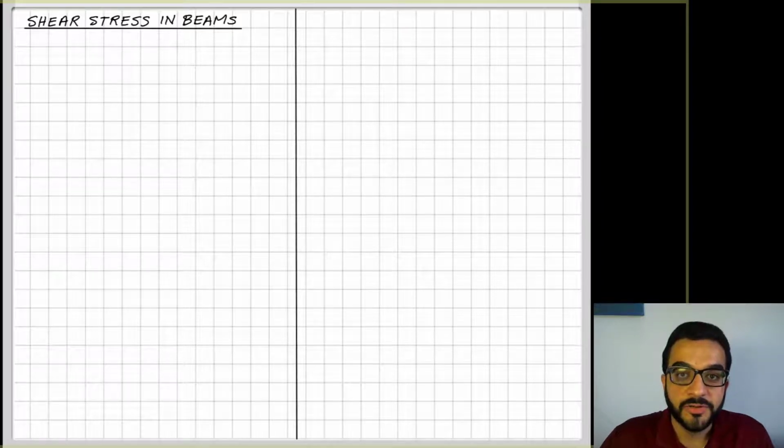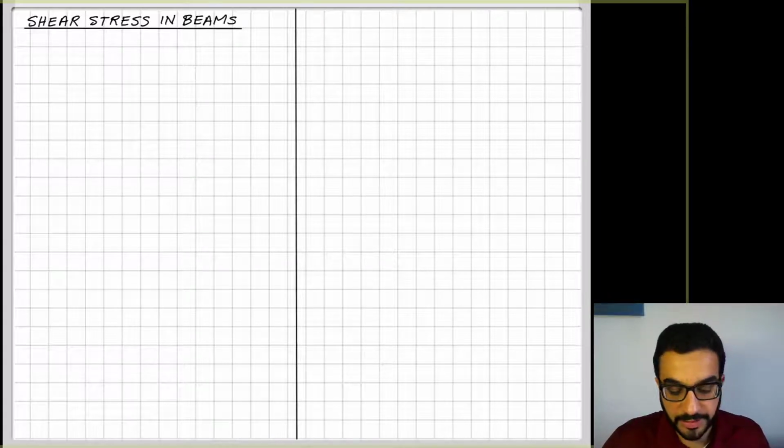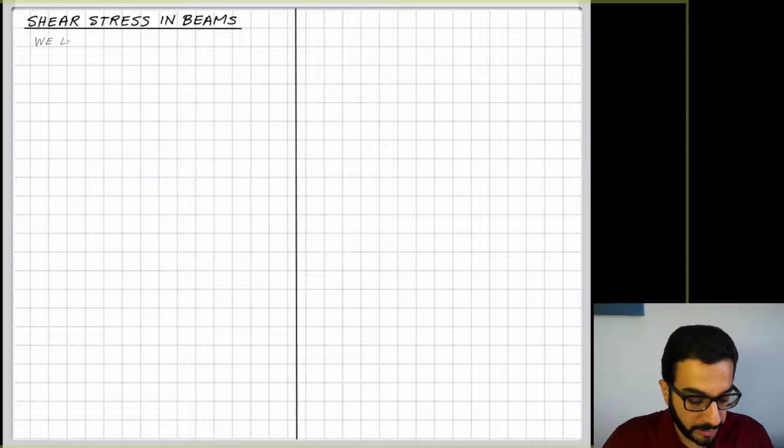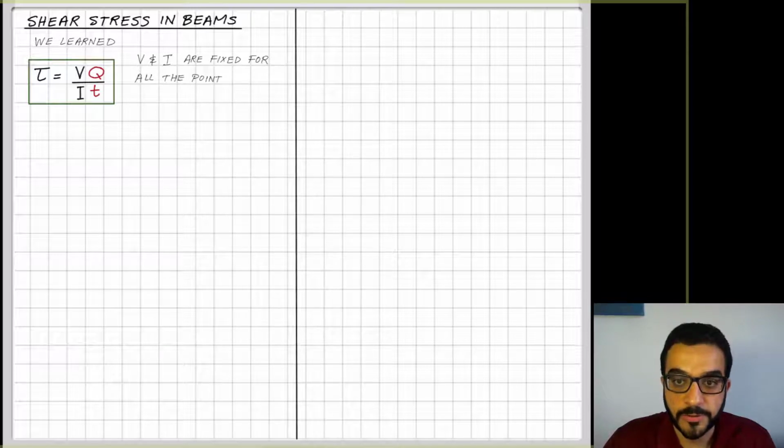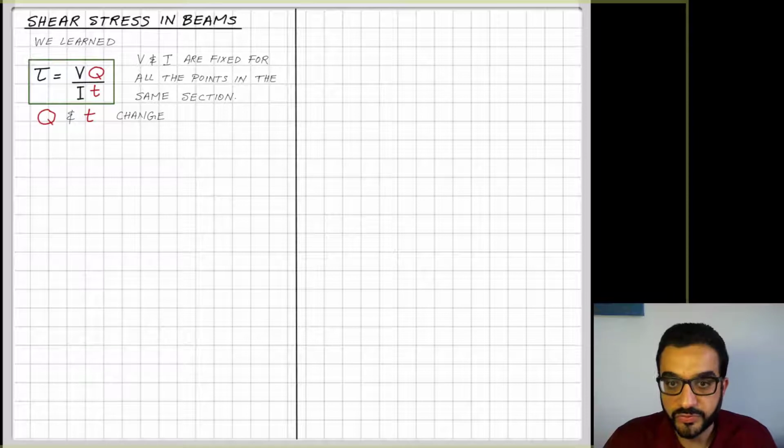Welcome. In this video we'll learn how to really understand more the shear stress development in beams under shear forces. Up to this point we learned the shear stress formula from a shear force. Tau is the shear stress, and tau is equal to VQ over IT.